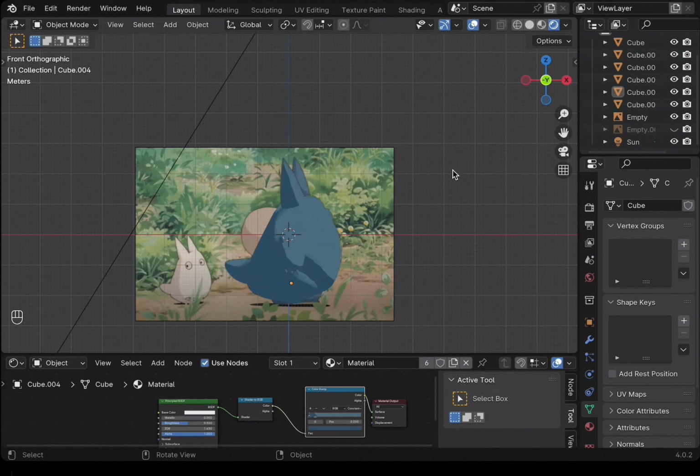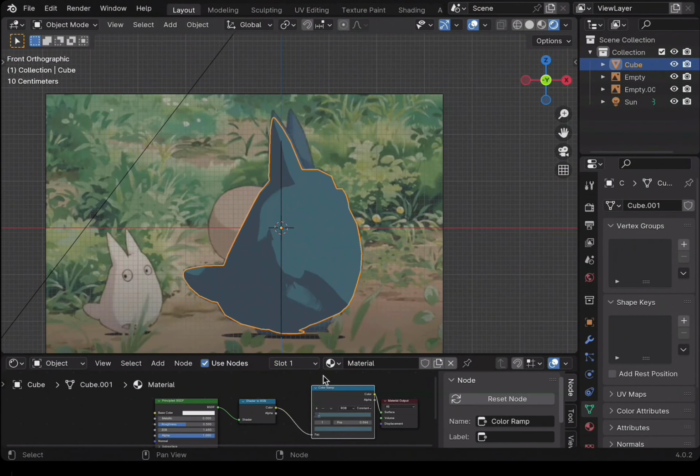I also tried combining all the parts into one mesh, but that only led to a weird effect with the grease pencil later. So keep yours separated for now. For adding material onto other parts of the object, create a new material for that part by clicking the copy sign to duplicate it. Tab into Edit Mode.